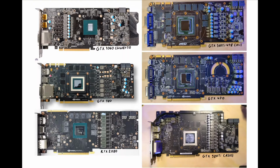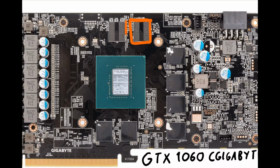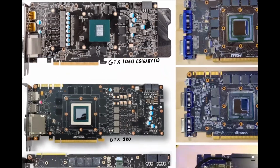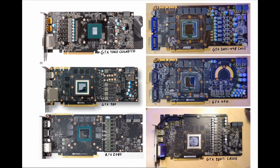So these are always the little black squares around the GPU, and sometimes you also have something like this. That is an empty soldering pad. Gigabyte probably uses the same PCB for a GTX 1070, which would have 8 gigabytes. So they slap 2 more on there to make 8 out of the 6 gigabytes on this card. That's pretty much the basic stuff, because every graphics card has a GPU and memory. You have that deviation with HBM memory, but since it's rather rare, that is the most constant thing you will find on every graphics card.